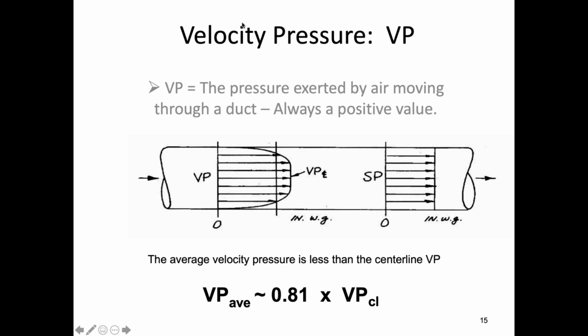What about the static pressure? Static pressure is always present. Yeah. You're measuring total pressure. Right? You're measuring the static pressure, which is there even when the air is not moving, and you're measuring the velocity pressure. So how do you adjust for that?